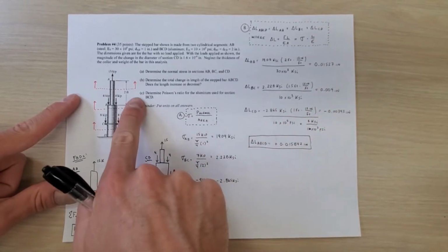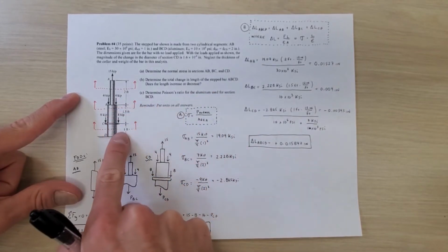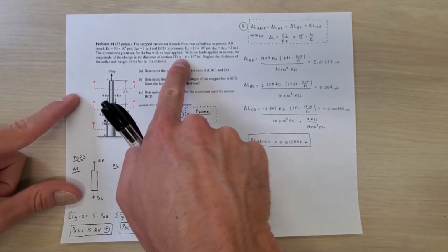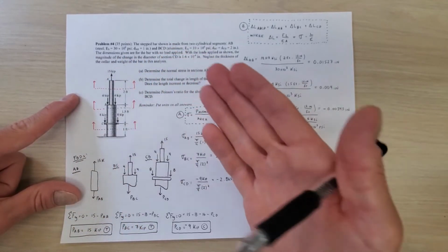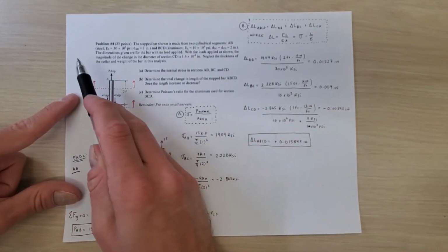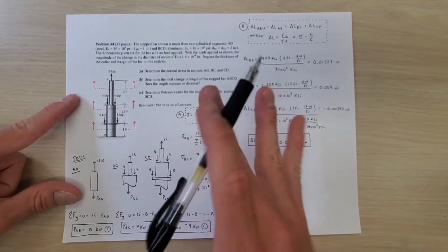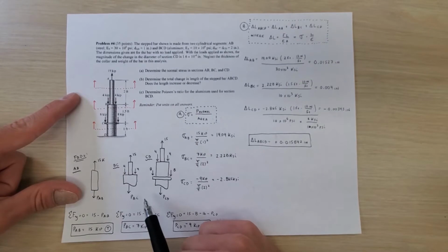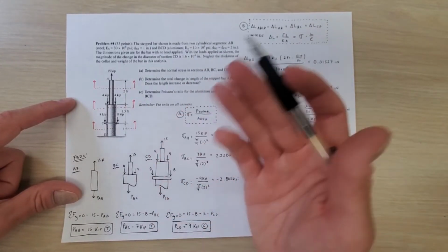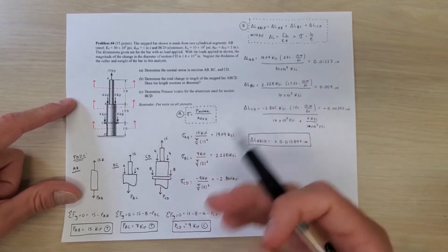Now, the last question is to determine the Poisson's ratio for the aluminum used in section BCD. We're told that the magnitude of the change in diameter of section CD is 1.6 times 10 to the negative 4 inches. So we know that change in diameter is going to involve Poisson's ratio, which we're given for neither of them, which actually that's our question here. So we're doing this question a little bit backwards than we might normally see in the class, is not to solve for change in diameter, because we're given that, but actually here we're asked to solve for the Poisson's ratio. So let me set up the equation for that and show you how to proceed.